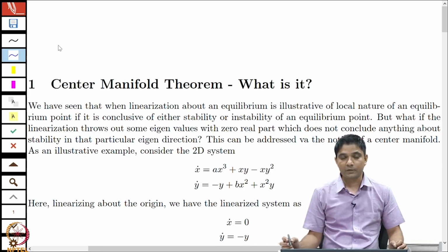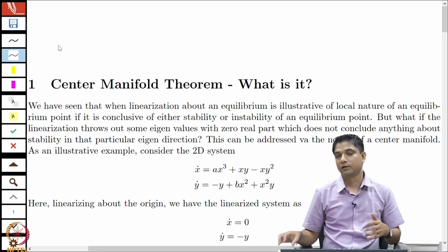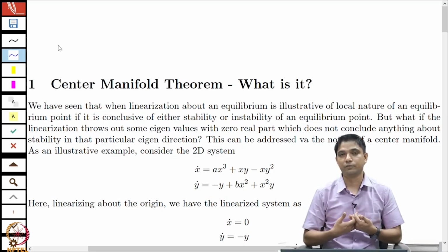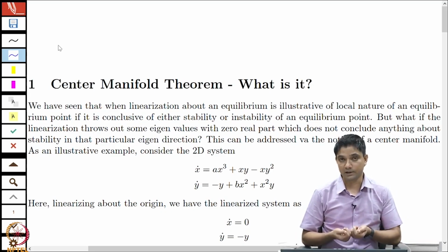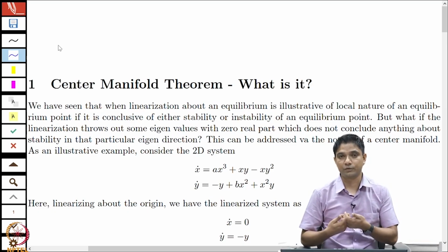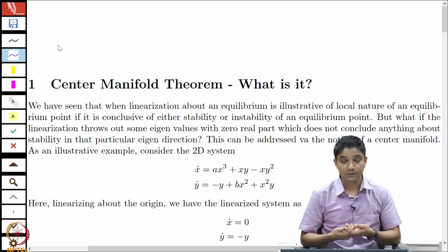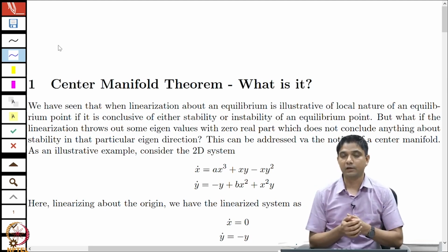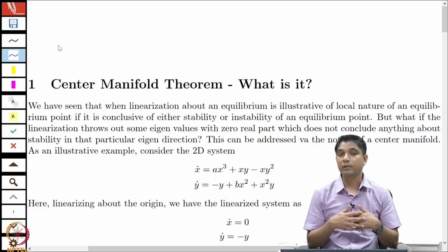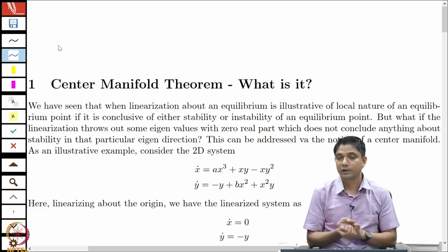topics. What we have seen so far when we talk of stability is, first we started looking at stability in terms of local linearization, which is also called the Jacobi linearization or the Lyapunov first method. There we just look at eigenvalues of the linearized system around a particular equilibrium point, and remember that stability was always defined with respect to a particular equilibrium point.